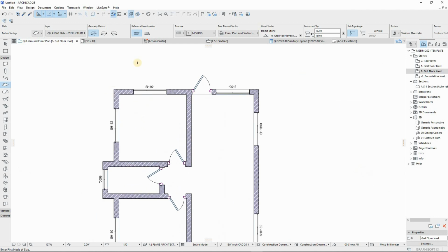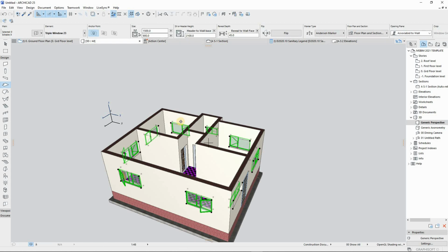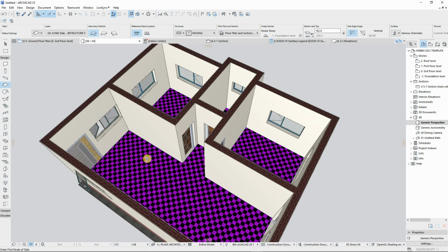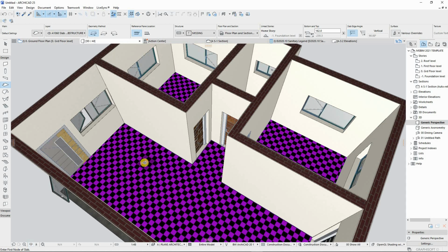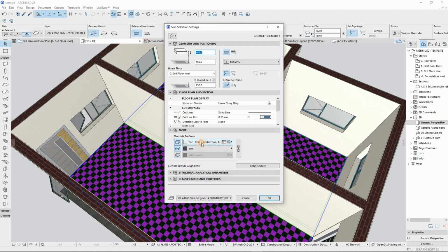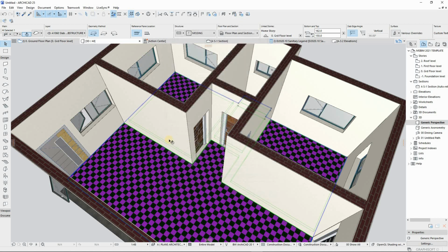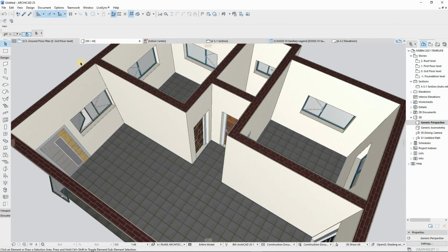So what I would do, if you check on the 3D, since we don't have the surface of this material, so what I'll do, like change it to something different or something else. So let's try check this. Perfect. Or we can create our own. ArchiCAD has hidden materials, that is hidden surfaces or textures that don't come by default automatically in your surfaces library.